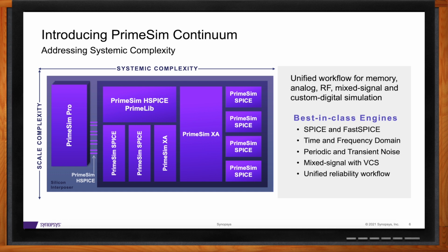It includes all types of analysis, such as periodic noise, transient noise, and it supports mixed signal simulation with VCS, and it includes a unified workflow for reliability analysis, supporting things like circuit checks, electromigration, and IR drop analysis, and aging, self-heating, and advanced variation analysis.